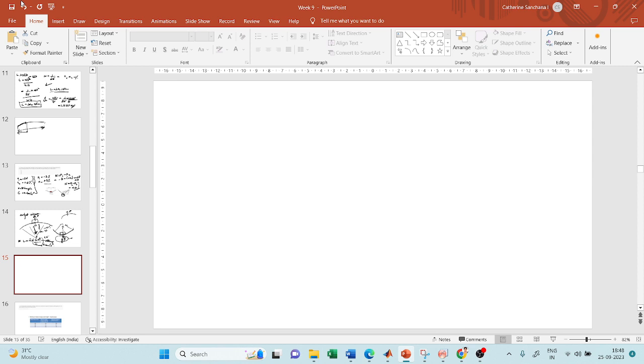The equation to find out the length of the curve in a summit curve was based on stopping sight distance, right? So here also you should have one formula equivalent to that. For a summit curve comfort criteria is not there, whereas for a valley curve comfort criteria is there.